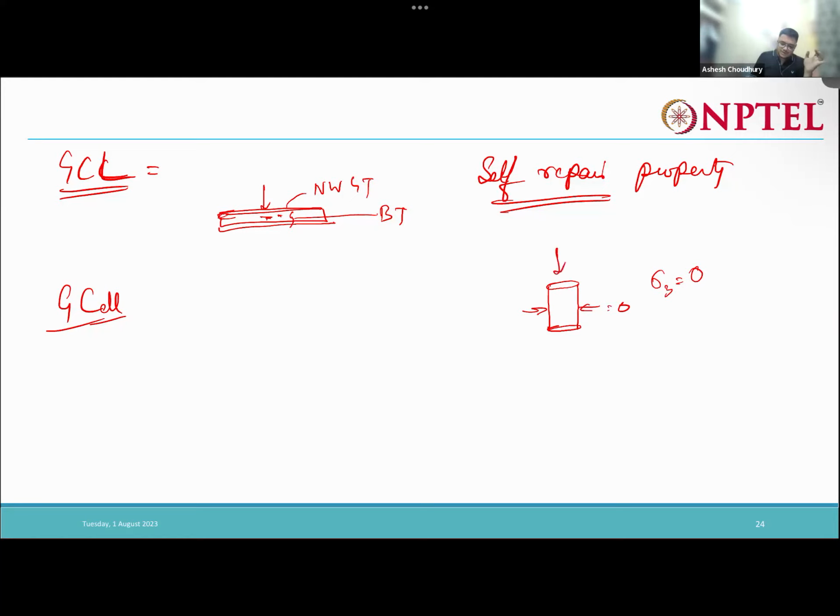If you keep on increasing the deviatoric stress or the axial load, it will fail at sigma d1. Now say we increase the confining stress to 20 kPa. At that time it will fail at sigma d2. Which is greater, sigma d1 or sigma d2? From common sense.